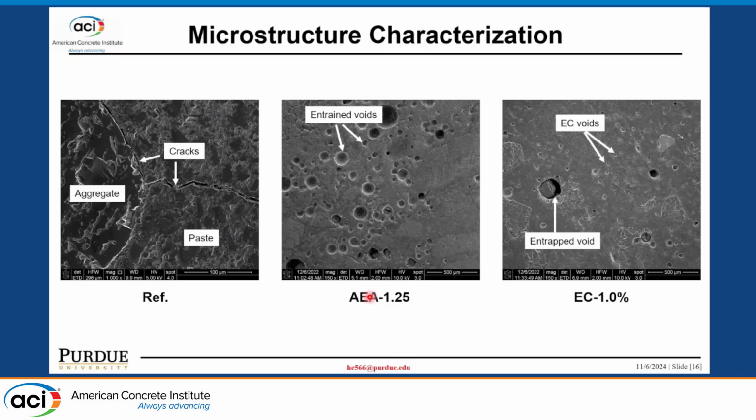After that, we did some microstructure characterization. So first is SEM observation. We can see for the reference concrete without the entrained air, a lot of damage, a lot of cracks around the aggregate, and the damage penetrates into the paste.